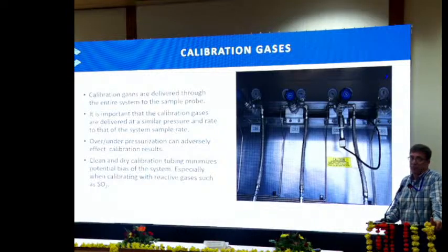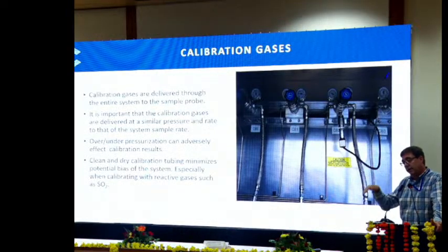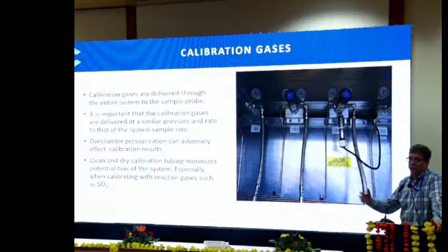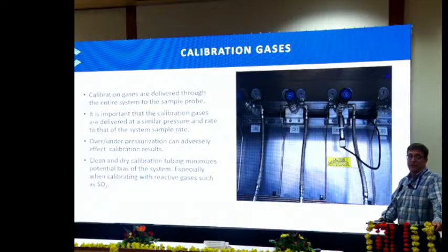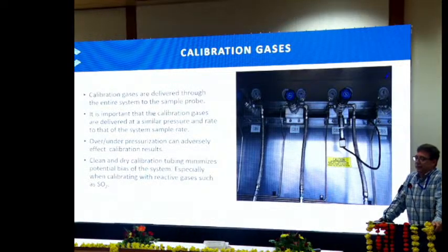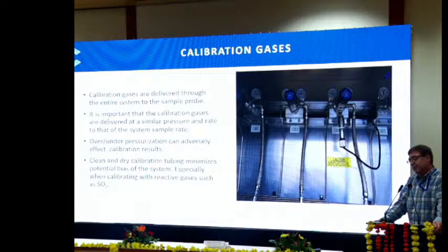They have their technicians go up to the stack test platform, or the platform where the probe is located, disconnect the lines, and rinse them with typically water or acetone, something along those lines, and collect that at the bottom and run it dry. It's important to make sure you run dry air through to clean out that moisture or any residue. That will cause a problem. So, if you're wondering why your SO2 or NOx are being funny,